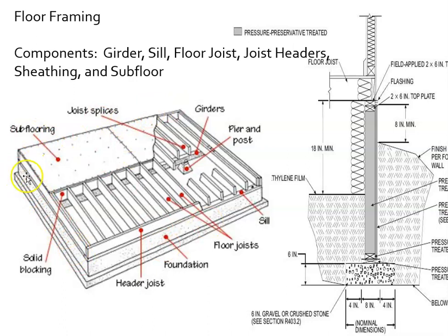This would not be considered a load-bearing wall. Perhaps carrying some weight, but as you can see, the great majority of, or really none of the joists are resting on it. This end rim board here is. So this is a load-bearing wall, girder in the middle, and then the joists bridge from the girder over to and sit on the pressure-treated sill. All right. Then we have, this is called the header joist or a rim joist.